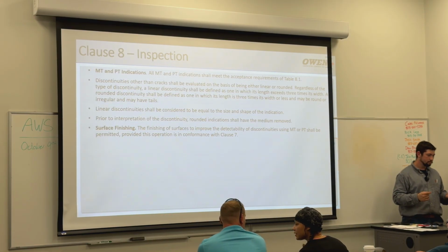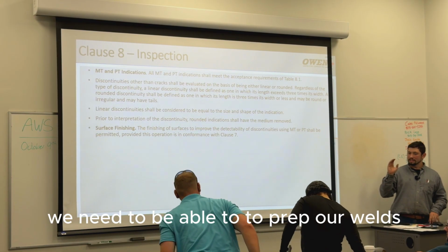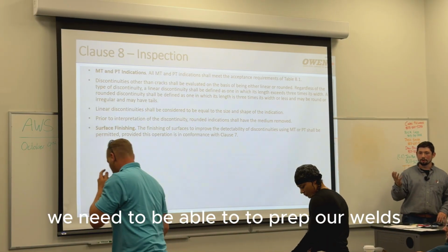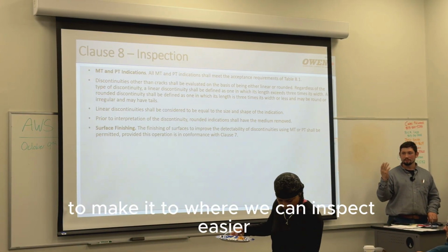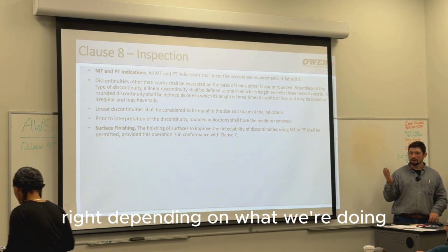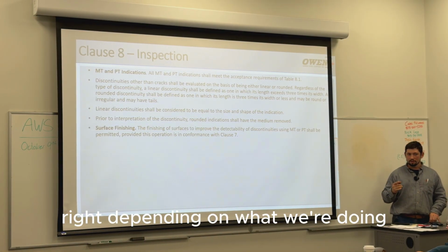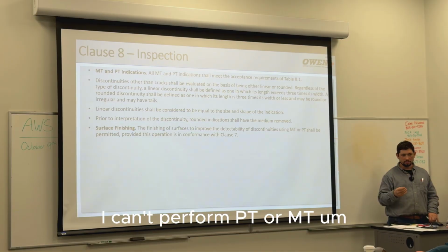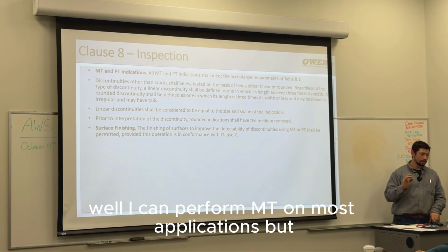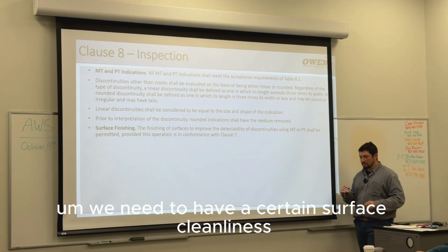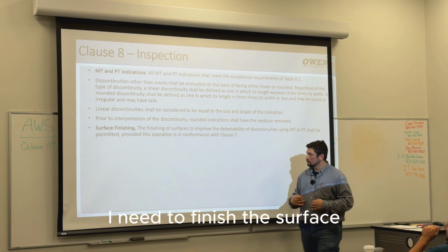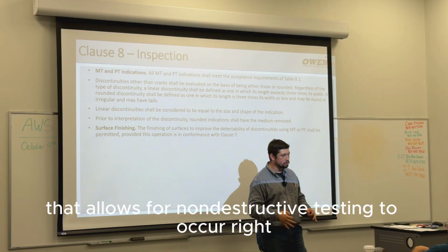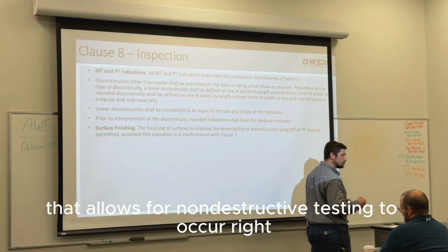Surface finishing. We need to be able to prep our welds to make it to where we can inspect easier, right? Depending on what we're doing, I can't perform PT or MT. Well, I can perform MT on most applications, but we need to have a certain surface cleanliness. I need to finish the surface that allows for non-destructive testing to occur, right?